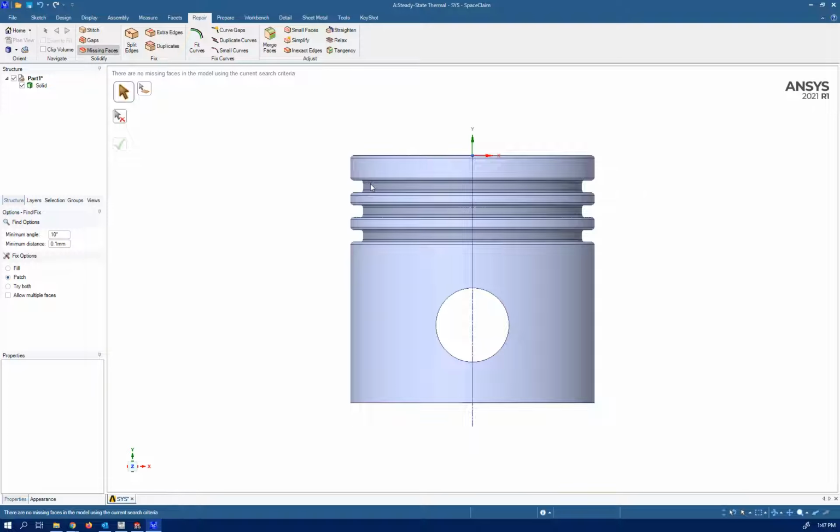But when you import in ANSYS, they may change a little bit, and ANSYS is going to figure out and say, okay, this is a complicated geometry. Later on, when you're applying mesh, it's going to be a problem. So I can ask to simplify those geometries. If there is a straight cut, make it a straight cut. Don't cut that line into several pieces. So let's check if we can simplify. It says 28 areas can be simplified. So why not? Let's simplify those areas.